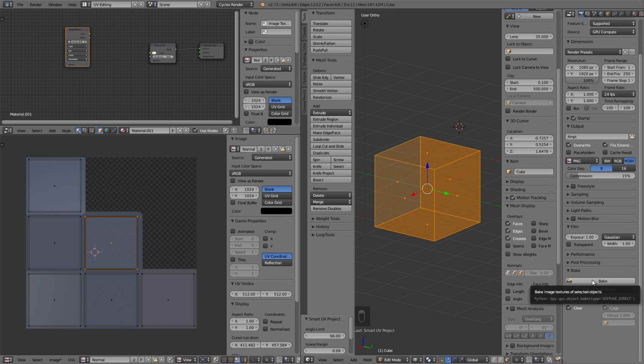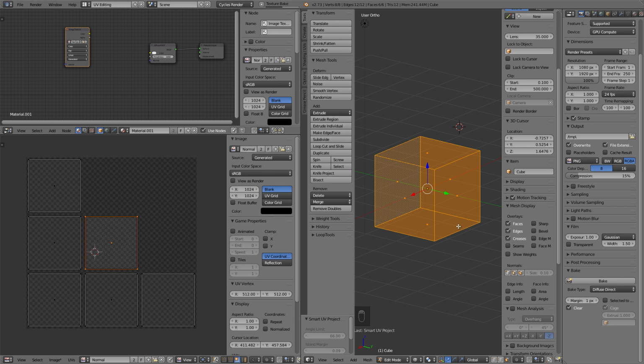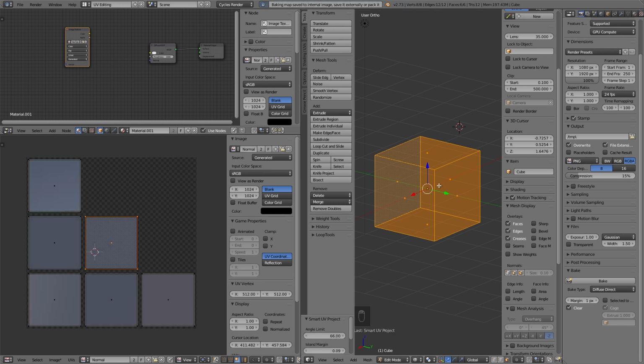You're absolutely right there. In games, if you use a margin that's too low, errors can occur. There can be actual gaps in between the normals or in between the seams, and hideous black lines can occur. But usually in Cycles 1 pixel is more than enough, because Cycles is not real time, so it has a lot more time to calculate all of these, and thereby it can do a much more precise job.